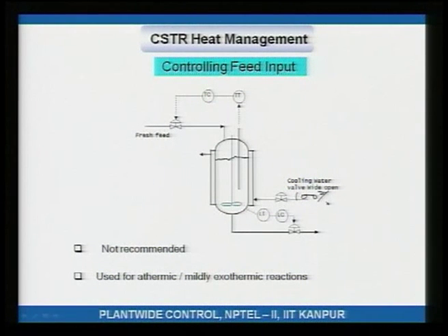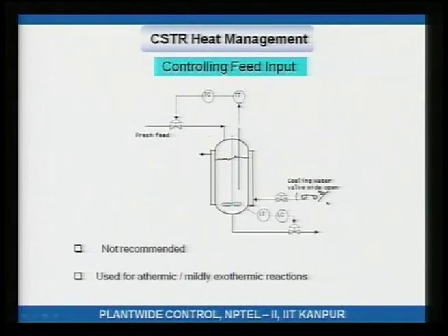Well, if the reactor temperature is increasing, that means I have put in too much reactants. I need to reduce the amount of reactants being put in. That will reduce the composition of the reactants inside the reactor, and if the reactant concentration is more, reaction rate will typically be more. If the reactant concentration is less, reaction rate will be less. This is mostly typical. So, if temperature is increasing, I reduce the amount of feed, reactant concentration goes down, amount of heat generation goes down, and the increasing reactor temperature comes back.